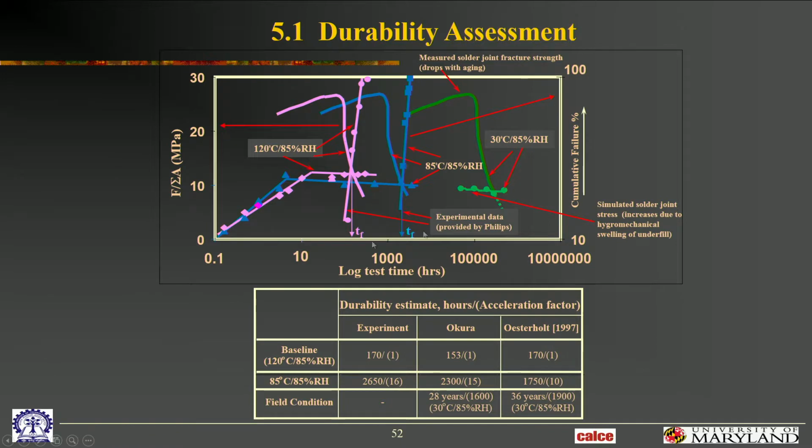And the model, this model at 30 degrees C, this was the degradation curve. Because this was getting so crowded, I just showed the last part of the degradation curve. It builds up from here and eventually comes here. And the intersection point is basically over here. So our prediction is that time to failure at 35 degrees C will roughly be over here, which is about 28 years. In the field, it'll last 28 years.